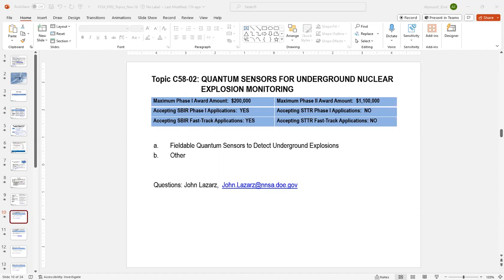Specifically, we're interested in methods that would lead to sensors that are fieldable in rugged environments. Some example characteristics would be the ability to deploy the sensor in any orientation in the Earth's magnetic field, data rates of 2,000 samples per second for millisecond timing resolution, and the ability to operate in a broad range of temperatures.